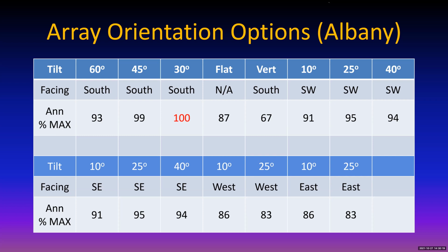They are improving on the temperature performance of these modules, and it's possible that whatever was downloaded referenced an older module from maybe 15 or 20 years ago, because this 0.36 refers to this modern 440 watt module we're looking at.